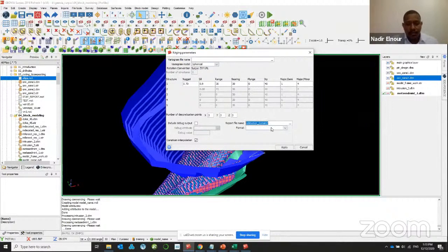You just need to give it a report name: Estimate number 1 nodes. Then you need to constrain the interpolation. So now we don't need to estimate the whole model. We just need to estimate inside that zone, because the samples we have are inside that zone, and we call this a hard boundary. This is now a hard boundary domain, because this is a lode and vein deposit.